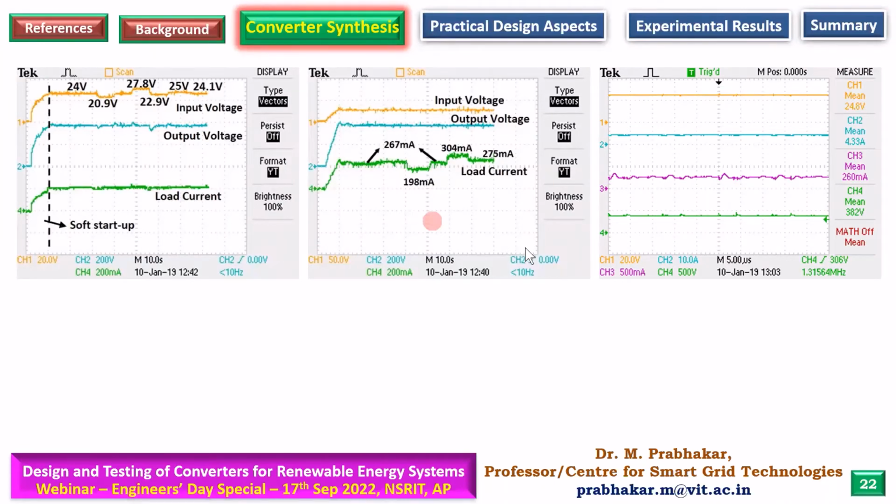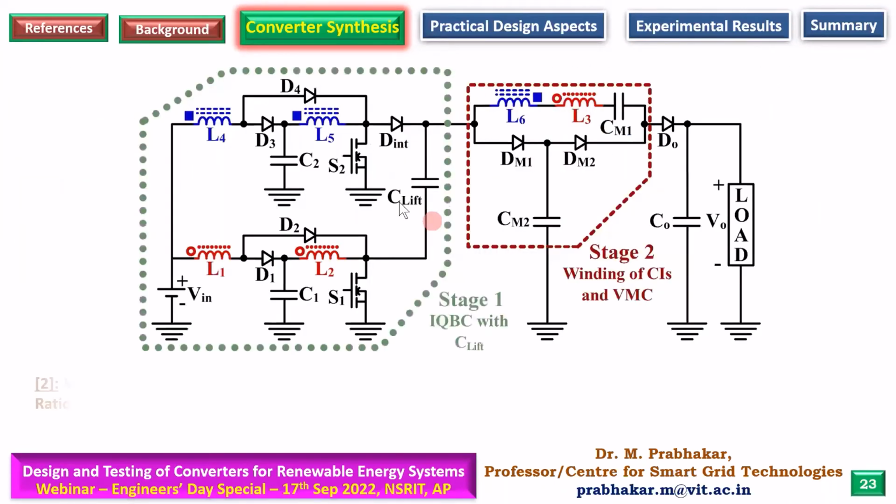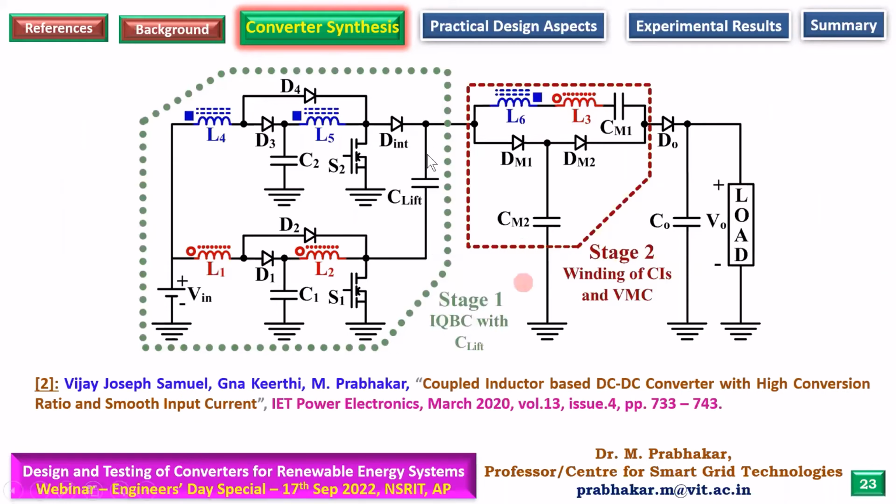Now, the next converter, we had a switch here. We stopped with this. We got a voltage gain of only 2 by 1 minus D square. We wanted to extend that because the switches were having a very high voltage stress, 50%. So we thought of introducing voltage multipliers.